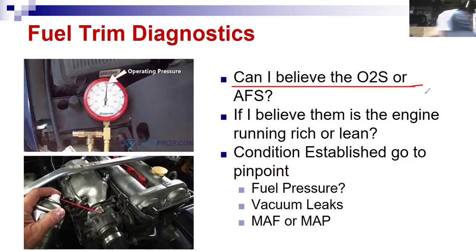And then you're going to see positive fuel trim numbers, and maybe it's actually making the engine run way too rich. Now, this was much more common on our OBD1 vehicles because they didn't have as good diagnostics built in for monitoring the oxygen sensors. They didn't have a rise time test. They didn't do a warm up cycle, so they would just blindly listen to what this thing said. I had a Jeep once, it had 11% CO. I mean, it was running so rich, it was like black smoke out the tailpipe rich, and it was nothing more than a defective oxygen sensor, okay?